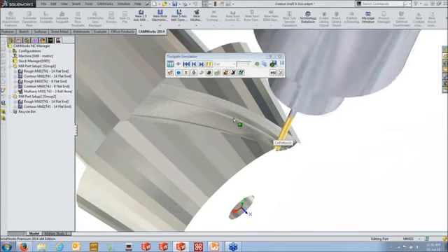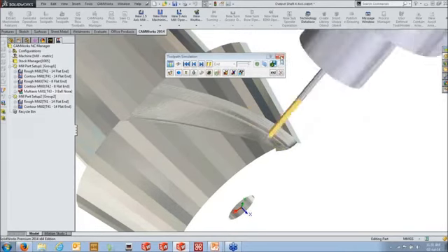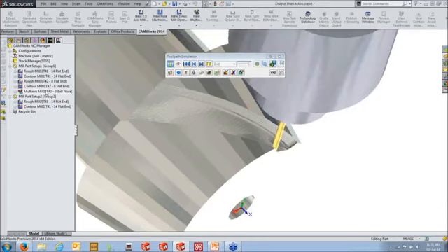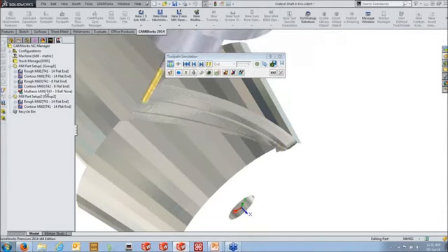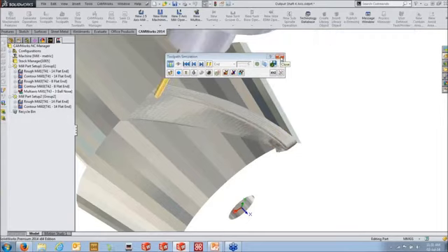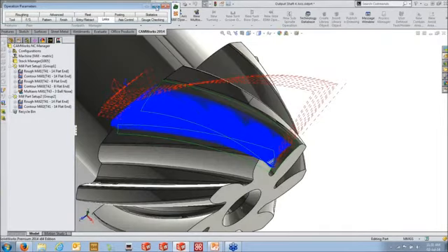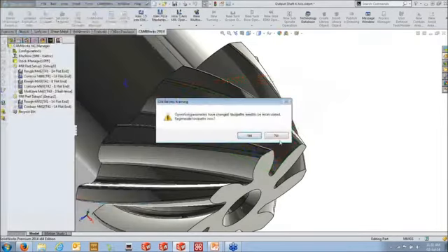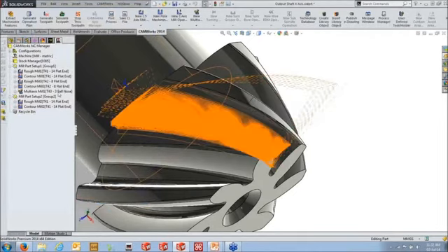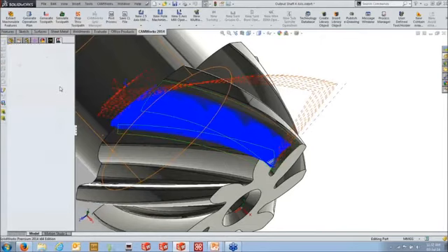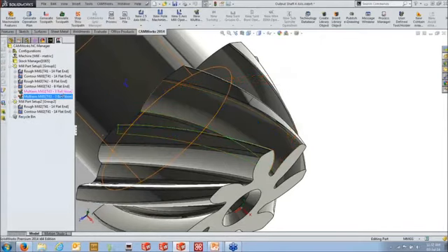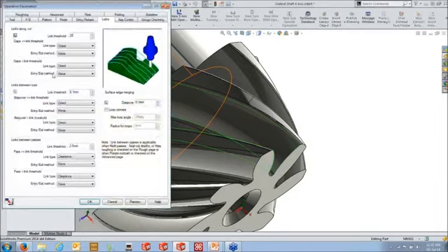And then as far as the finishing path goes, we can just copy that particular operation, the roughing operation, maybe remove some of the parameters and then regenerate it without the roughing options. So if we go back in, we'll click OK and define that. No need to regenerate since we've already got it. The fastest way I think of creating the finishing pass is just control drag what you had, bring it down beneath it, go back in, and redefine some of the parameters here.